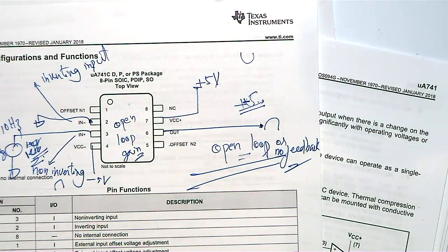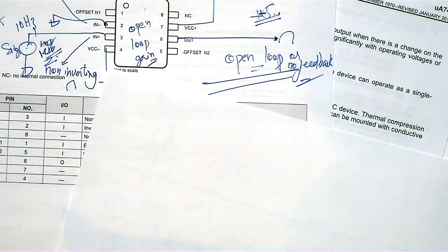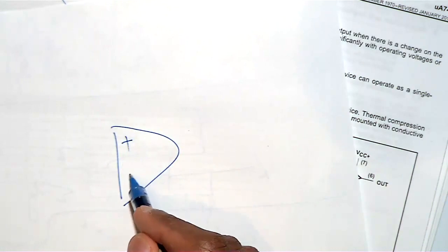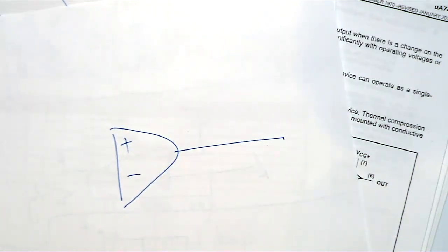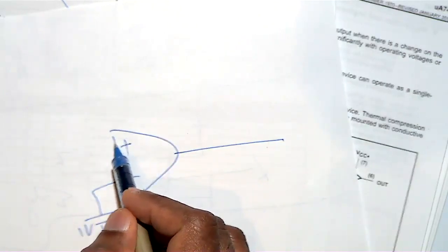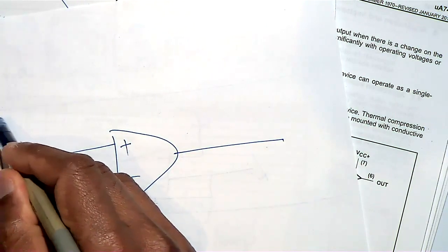In the comparator, what it does is it is comparing two signals. Comparator means you take an operational amplifier, then this is positive, this is negative. As I said, you want to compare two signals. You want to have an output when the input is exceeding some voltage. So what I can do is I will connect here 1 volt. And then here I can connect a varying signal like this, 0 to 1.5 volt.